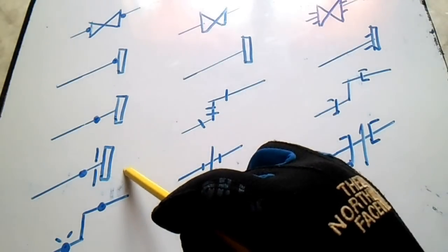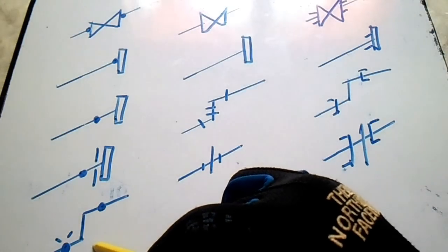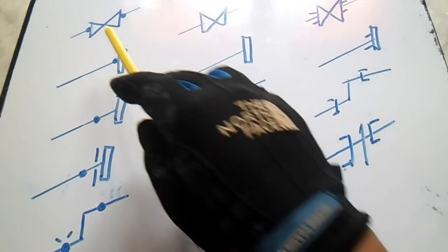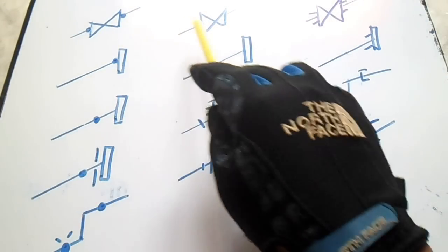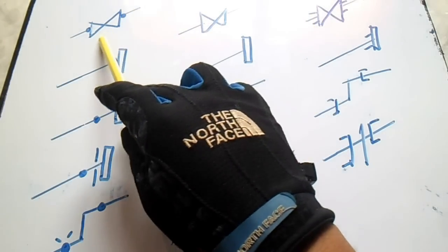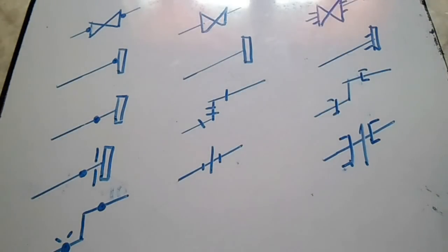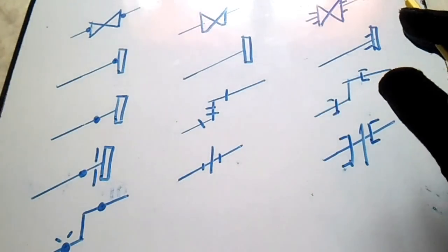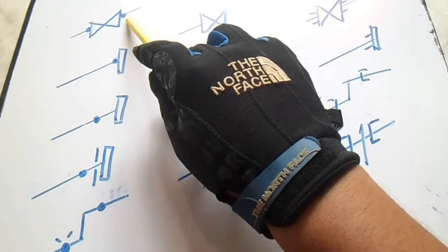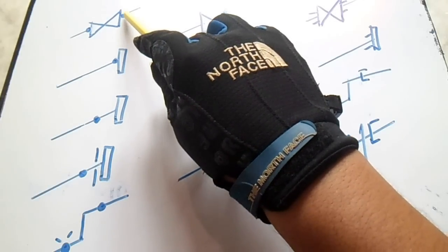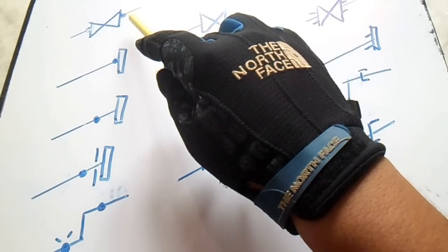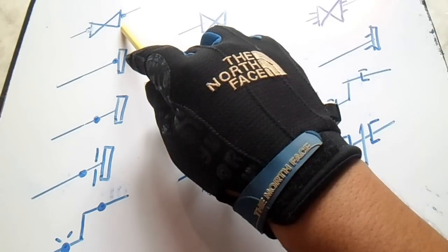This is a lap joint, and we have a 90 degrees elbow. If you can see, they have a difference from this gate valve. So we have 3 gate valves, and they have different symbols or different joints. If you see this dotted line, it means this is a butt weld. Butt weld.